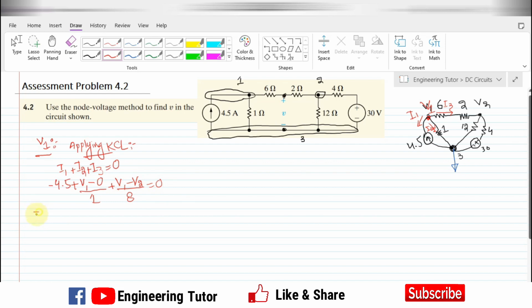Let me simplify this. Moving this minus 4.5 to the other side of the equation, we get V1 plus (V1 minus V2) divided by 8 equal to 4.5. Taking the LCM, which is 8, we get 8V1 plus V1 minus V2 equal to 4.5 multiplied by 8.